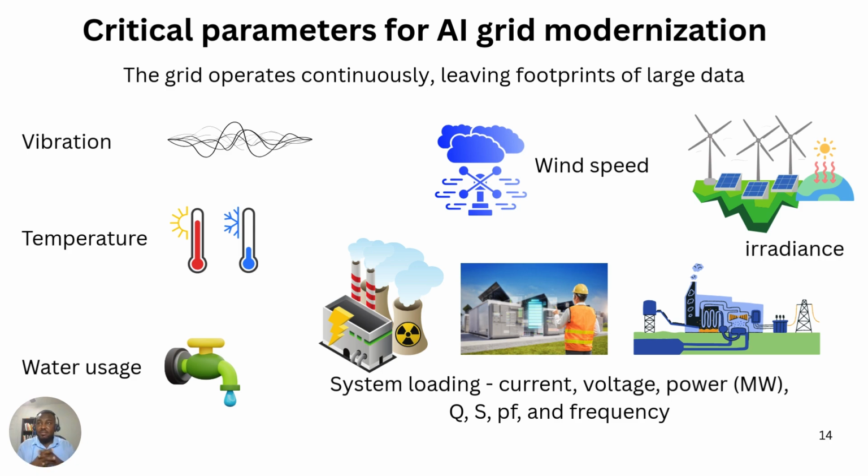So this temperature difference plays a key role in design parameters, from how you size your cables to how inverters operate, for instance if you're running a solar plant. There's a derating based on temperature conditions. So we need to know this critical parameter very well. Water usage.